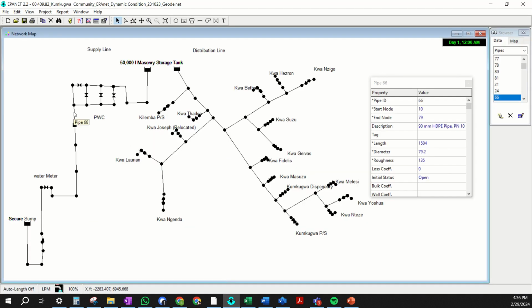And we basically need to model all this piping in the treatment and going to the tank. So our treatment piping is 3-inch PVC. We have 2 pieces of 3-inch PVC. And then we have 3-inch GI. And unfortunately, those are different. So the best way would be to model them as 2 separate pipes. We can't do that, but they're very close in diameter. So we can just model this all as 1 long pipe, 4.5, 3, and 3. That's a total of 10.5 meters.